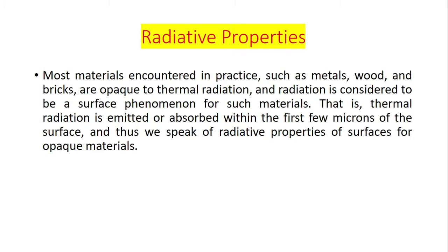So the materials such as glass and water are semi-transparent to visible radiation, but at the same time they are considered as opaque materials for infrared radiation. So it depends on the incident radiation. For visible light, glass and water are considered semi-transparent, so a part of the radiation is absorbed, and in the case of infrared radiation, the glass and water are considered as opaque materials.